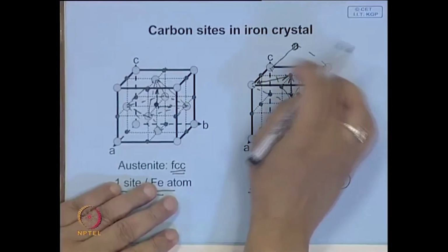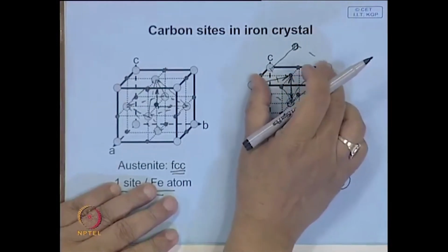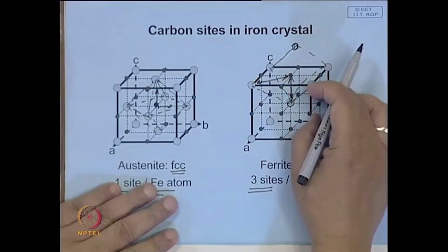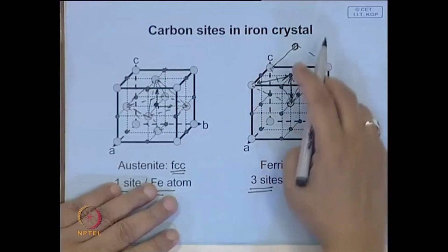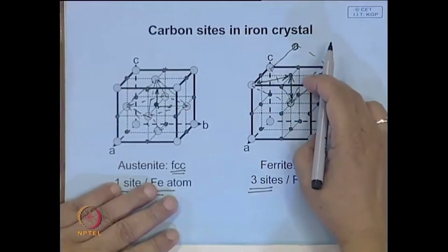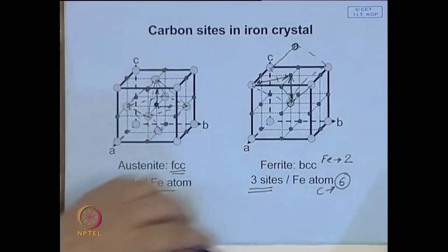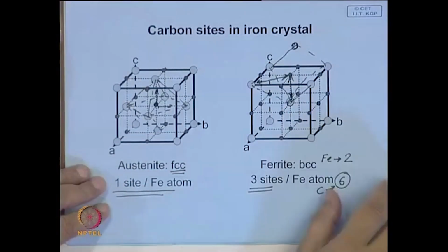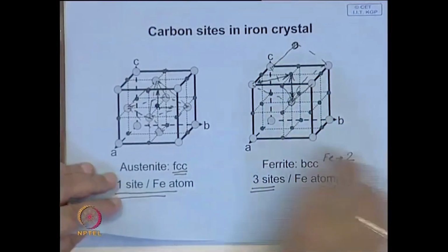In this direction it is so large that these atoms can even come closer, whereas this side is much less than the atomic diameter of carbon. So, on this side these atoms will be pushed apart significantly, and this leads to an asymmetric lattice distortion, which has a much stronger stress field than this.